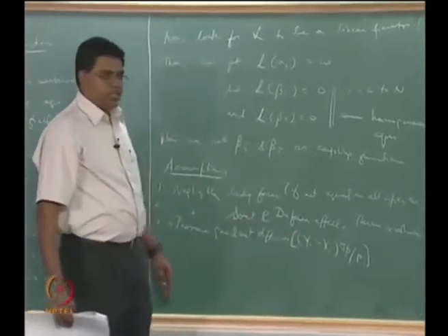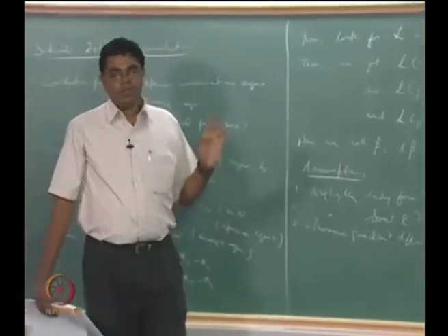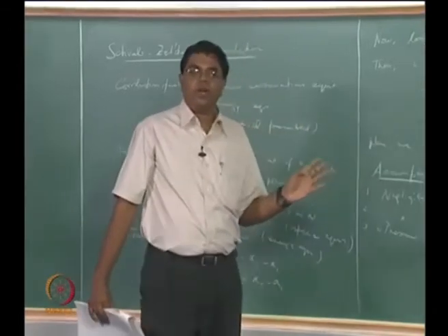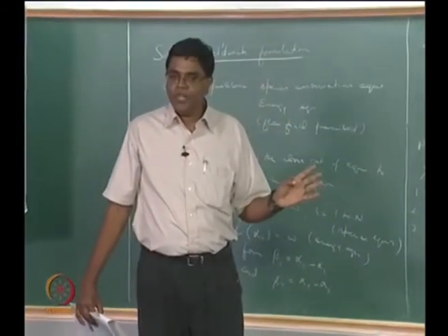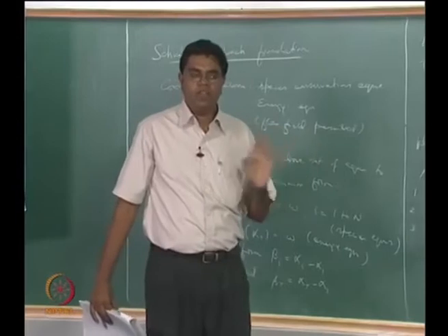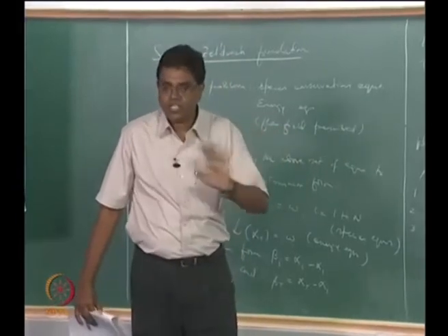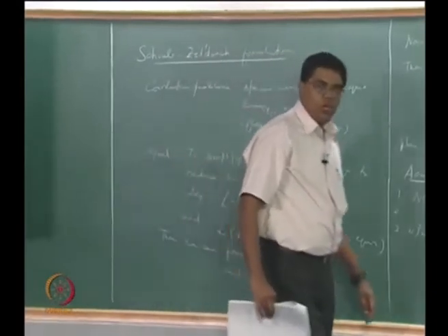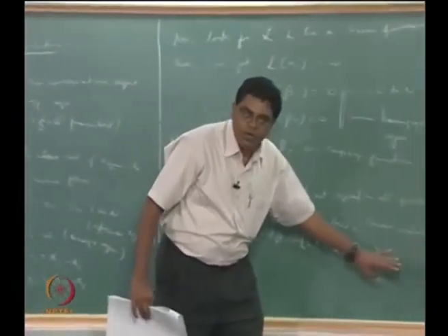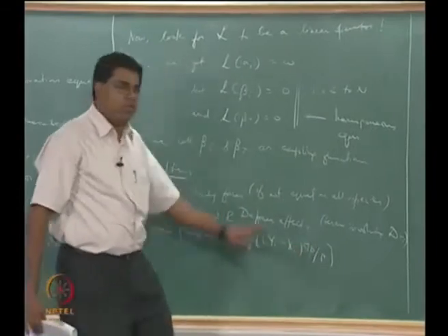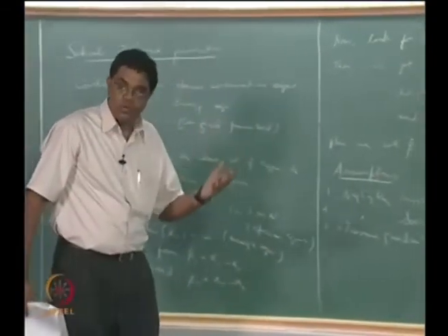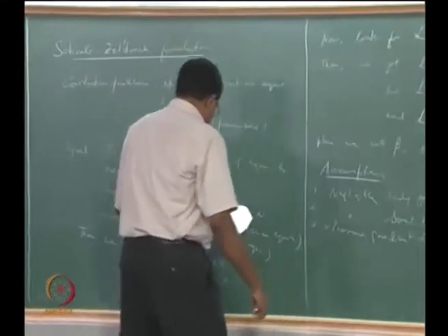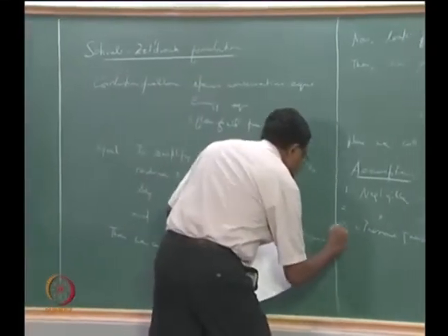The third way of actually trying to justify this is, in the previous class we found that for low Mach numbers the pressure is almost a constant. It affects only your flow field, but it doesn't really get into your combustion field a lot, right. So as far as the combustion problem is concerned, we could simply say the grad p is very small, right. That's the reason why we want to say the diffusion associated with it is even smaller, right. Okay, so that's reasonable.